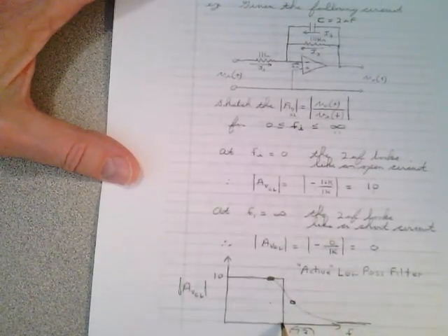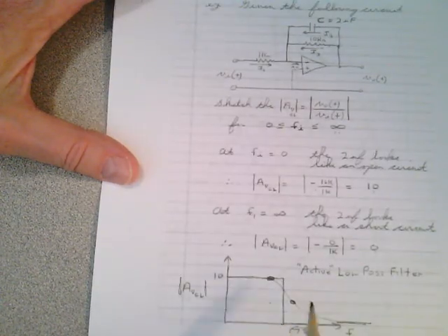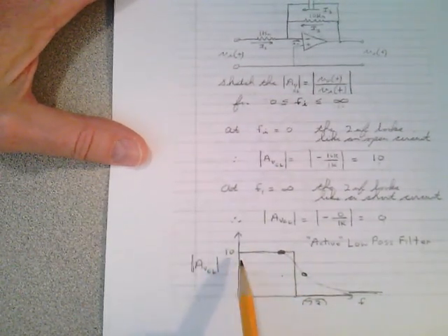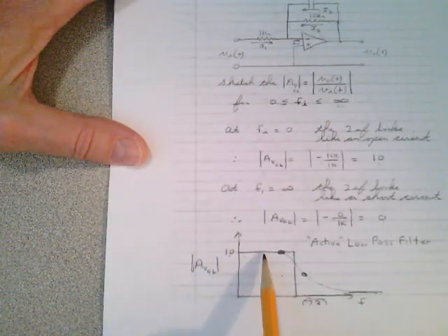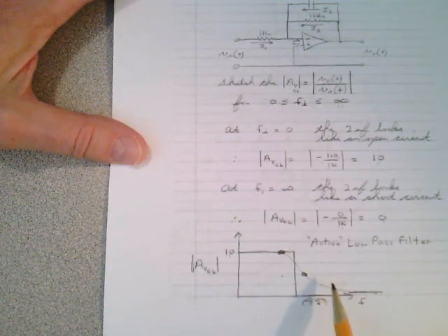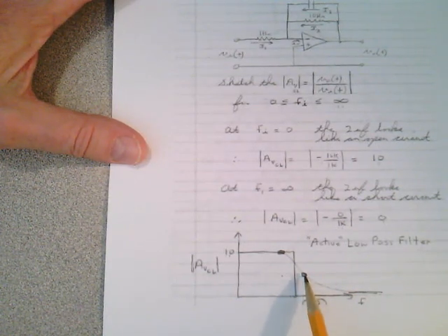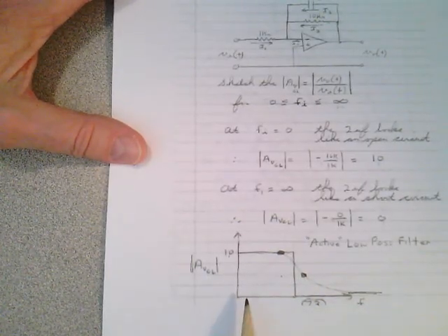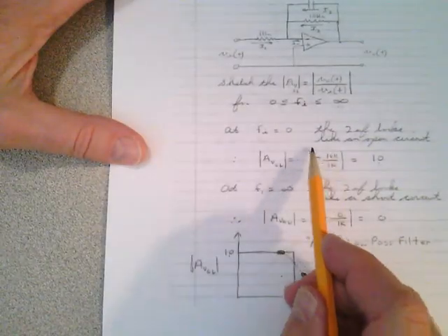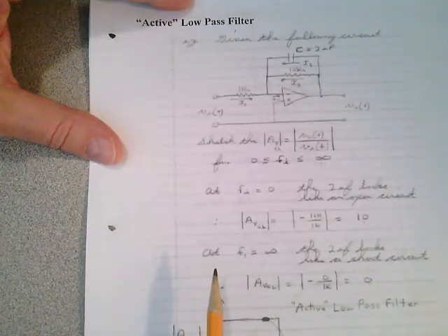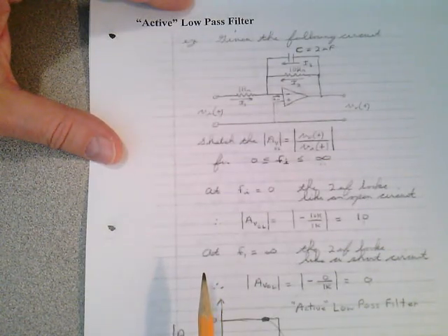Now, there isn't an abrupt transition like this. You already know that. It's a gradual thing. You'll see on our Bode plots later on. But if you look at that, you can see that is a low-pass filter. It passes the low-frequency signals with a gain of 10. And anything above whatever this break frequency turns out to be, which we'll calculate later, it kills the signal out. And you should be able to see that through what I just explained here. Or just simply look at this, and at the high frequencies, that looks like a short. And there's absolutely no gain to that circuit.